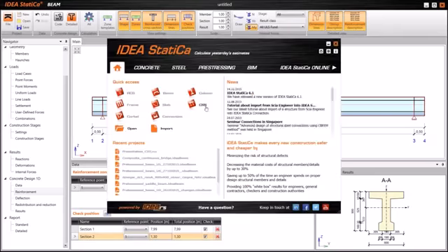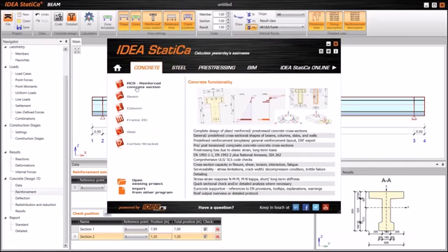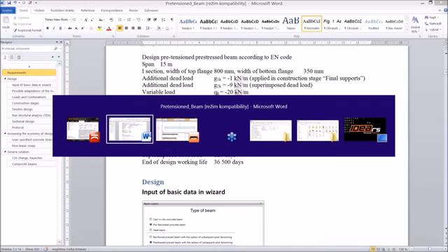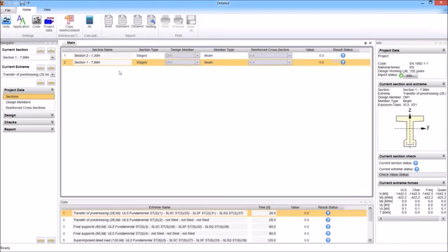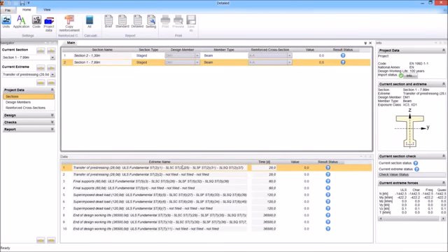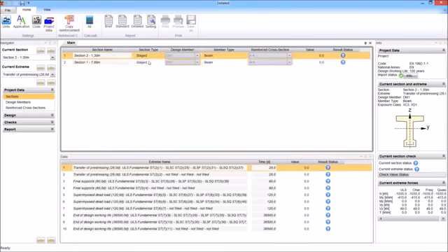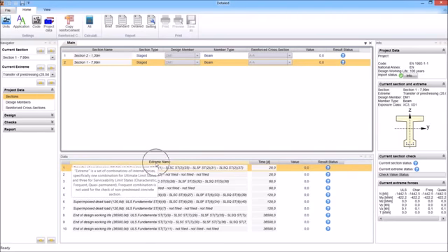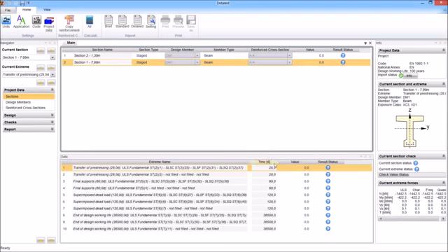And you will see that RCS is a standalone reinforced concrete section program, which we also linked to this beam program, and the program generated the data for you. You can see two sections at 1.3 meters and at midspan, and also several extremes, which are at 28 days, 60 days, 120 and 100 years.